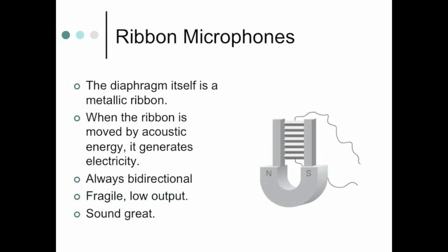And as I mentioned before, the parameters of sensitivity and frequency response are interrelated because low frequencies have more energy, high frequencies have less energy. As the frequencies start rolling off in energy, or should I say, the microphones themselves have a threshold of the amount of energy it takes to move the diaphragm and create a signal out. So a moving coil dynamic has a higher threshold, so it needs more energy, which necessarily means it can't have as good a frequency response as a ribbon microphone. And of course, as we discussed before, it all goes back to the basics of spectrums: when you can hear higher frequencies, things sound more lifelike because you can hear the spectrum better, which makes it sound more like what it's supposed to sound like.